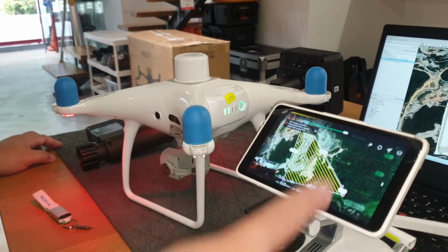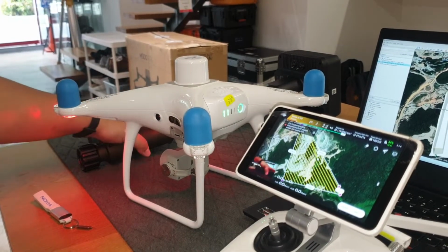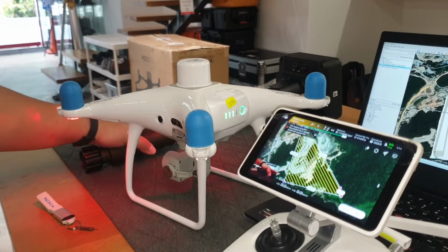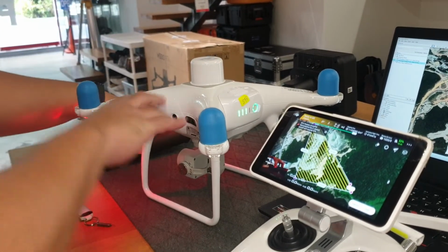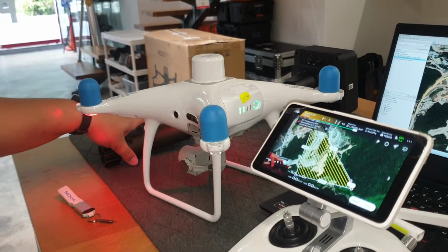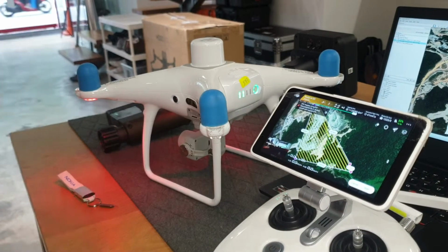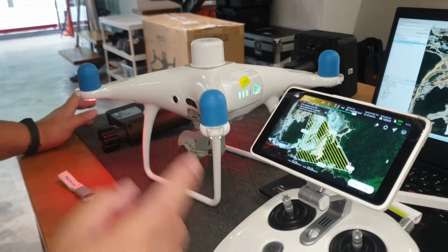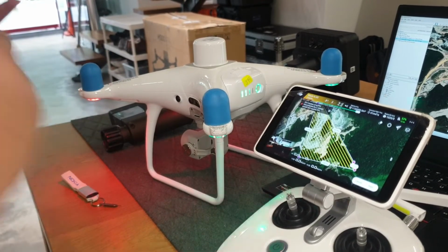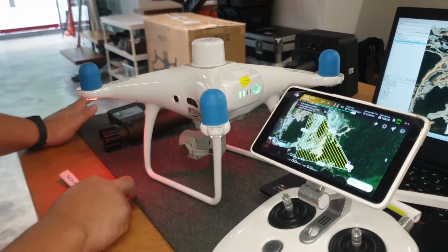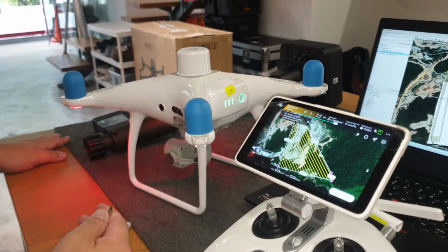So the tedious part is the initial setup, measuring your GCPs and then measuring the known point where this is placed. But once you've done the final link where both of these are linked to here already, then it's pretty repetitive. Even if you switch the batteries anywhere, it will just keep on working. It's the first phase where you're switching modes and things like that that makes room for error. But other than that, that's basically how the setup works.